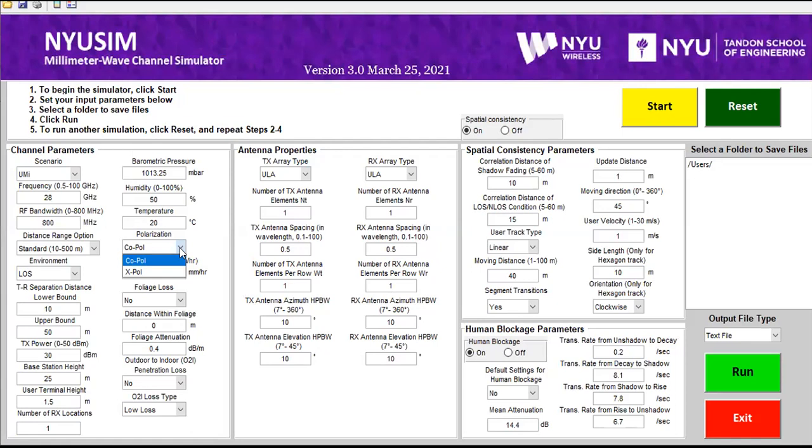That orthogonal position will not allow any signal reception, so that is ideal, but practically you have some reception. Secondly, the non-LOS environment delivers the signal in different forms. The polarization for the different versions is not alike. You don't have that strict requirement of polarization in a non-LOS environment.